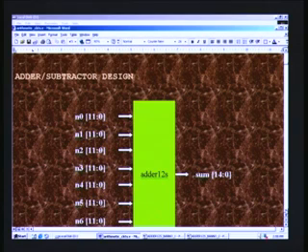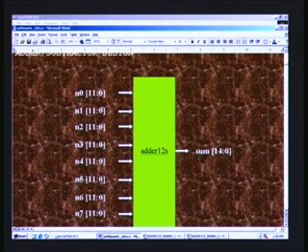First let us have this pictorially here. So we have N0 through N7 as 8 numbers, each of width 12 bits as we mentioned before, and the MSB is the 11th bit. This is the case for all of them. It is basically an adder cum subtractor, provided you have signed addition. You can use 2's complement in this, which we will see shortly. Finally a sum emerges here, and note that the width has increased here. Why the width has increased, we can easily reason out.